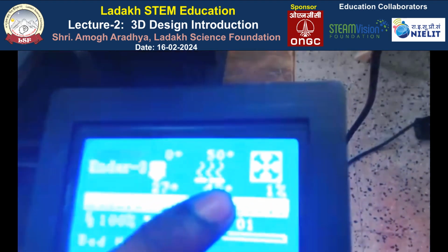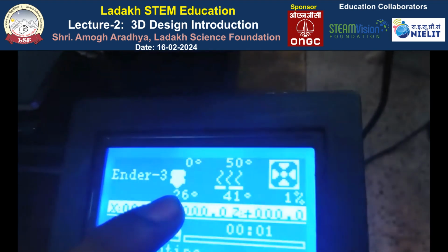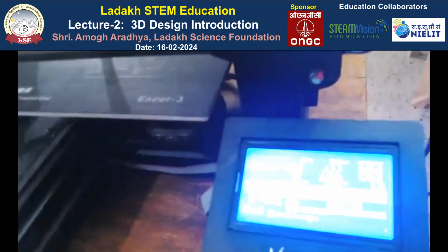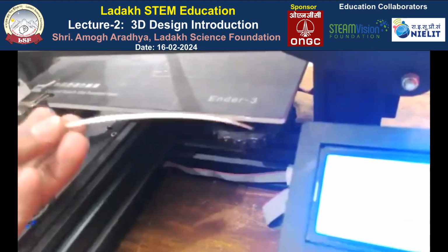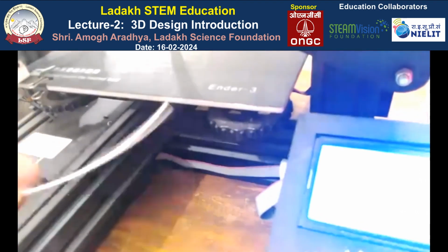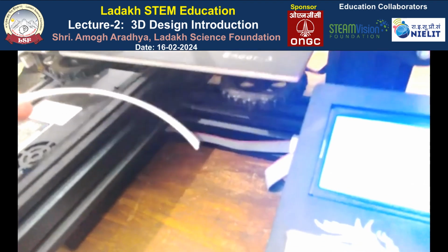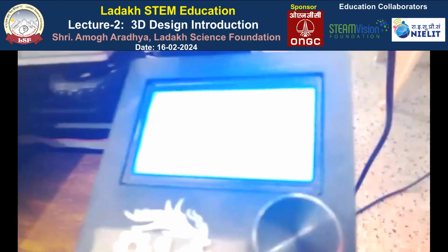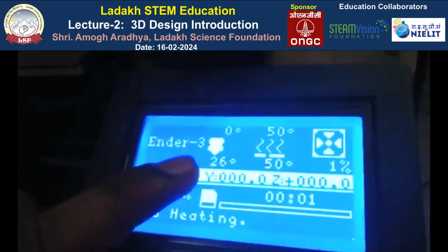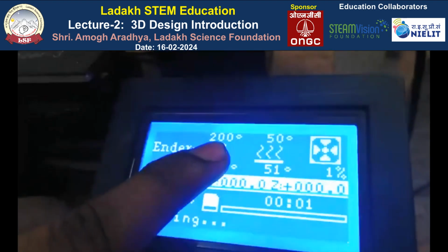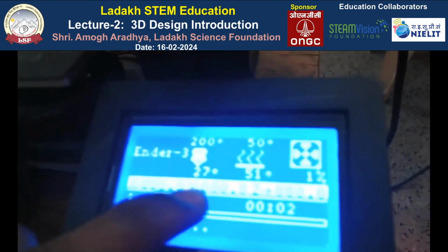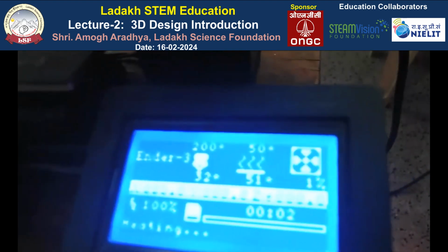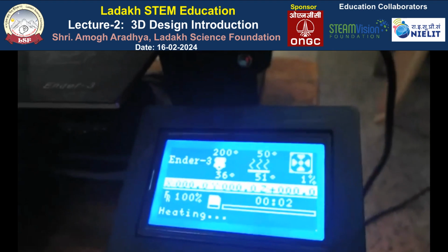This is the build plate. This is the nozzle temperature. Nozzle temperature is currently 27 degrees Celsius. So since this filament is made up of polylactic acid, the melting point of this filament is around 180 degrees Celsius. So the nozzle temperature will go up to 180 degrees right now. Okay, it's actually 200. So now it has started heating up. And yeah, this will take some time.